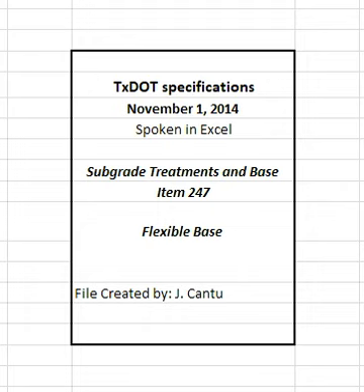When requested, furnish the engineer documentation for the person certified to operate the profiler. Provide all profile measurements to the engineer in electronic data files within 3 days after placement of the prime coat using the format specified in TEX 1001S. The engineer will use department software to evaluate longitudinal profiles to determine areas requiring corrective action.